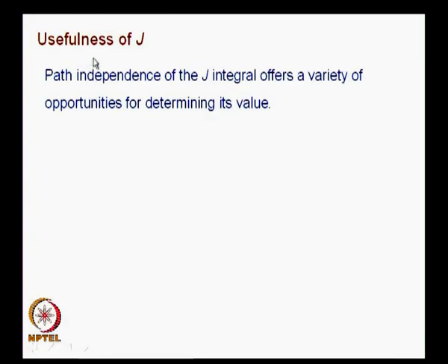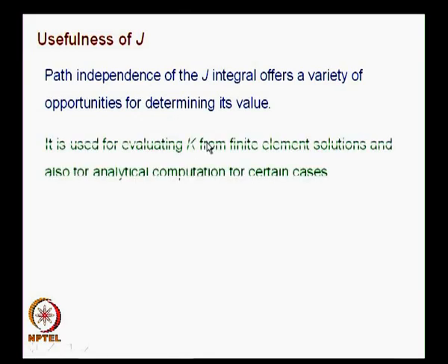What is the usefulness of J? Path independence of the J integral offers a variety of opportunities for determining its value, because I can choose a path which is comfortable for me to evaluate. It is used for evaluating the stress intensity factor K from finite element solutions and also for analytical computation for certain cases.